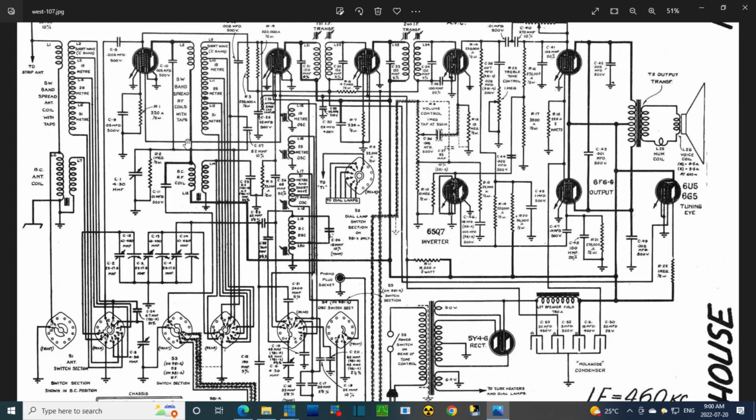Well, let's not jump to conclusions here. Did this burn out? Did this one burn out and this one not? If this one burns out, there can be no B plus on the tube here. And I don't think the AM signal would come through it. But we can conjecture all day. What I need to do is put a new capacitor into this position and then operate the radio and just see if it's come back to life or not. I also, because this capacitor is laid up right on top of this coil, the sparking may have damaged this coil, although I don't think so.